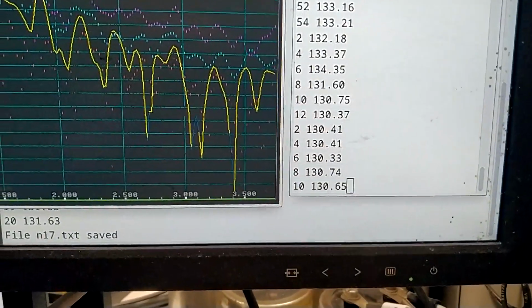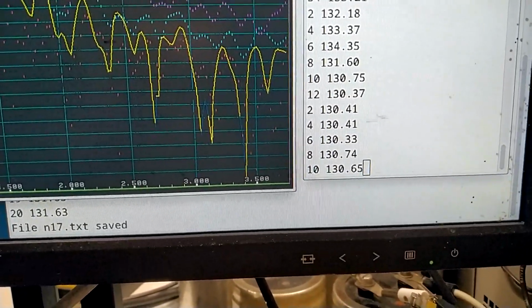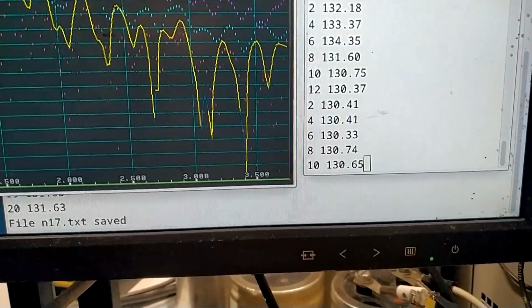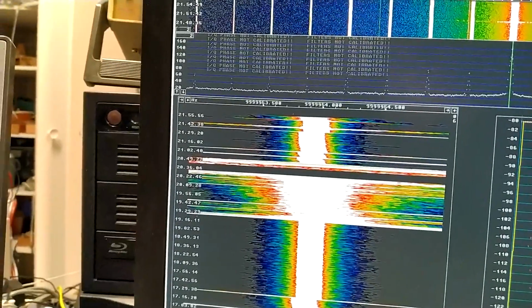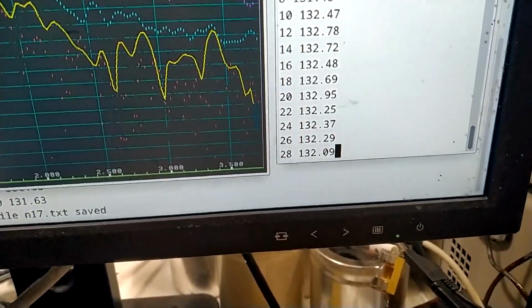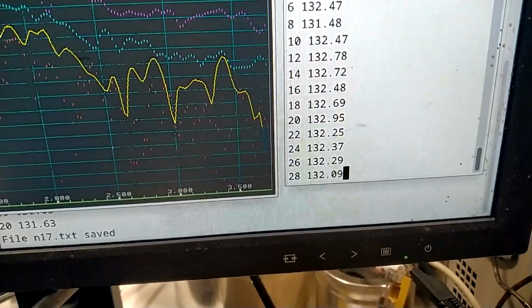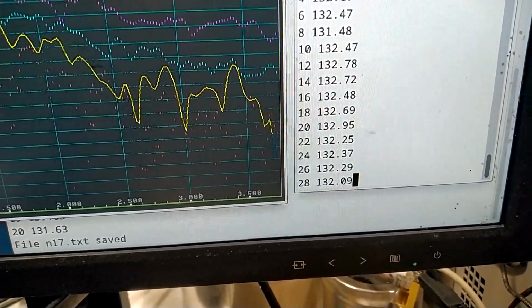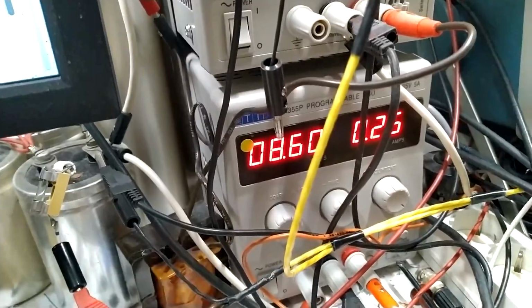The phase noise from 0.2 Hz to 3.7 Hz is degraded by 3 decibels on the average, while the temperature is rising. I will wait for a while to see if there is an equilibrium with less noise. This is 20 minutes later. The average noise is almost restored. The temperature is probably reasonably stable again inside the box, and not much higher because the power is only about 2 watts from that lamp.